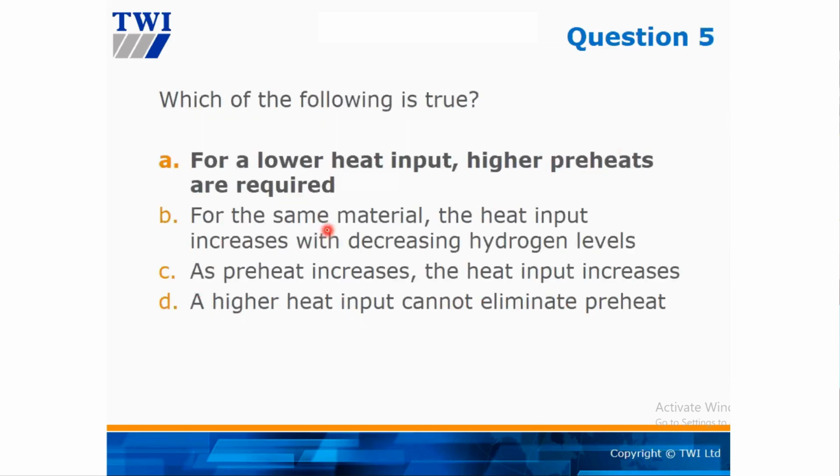All right, number 5, which of the following is true? The lower heat input, higher preheat. That's correct. This is what we need to refer to, preheat. Preheat factor. Preheat factor is hydrogen, heat input, thickness, and carbon equivalent. Yeah?